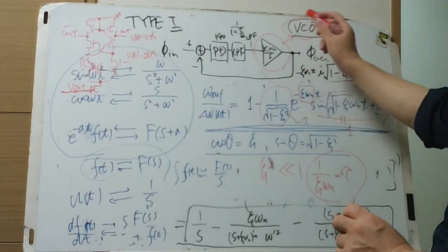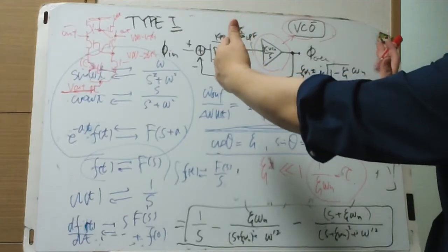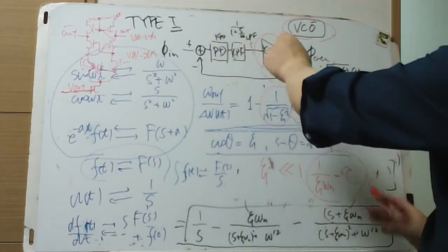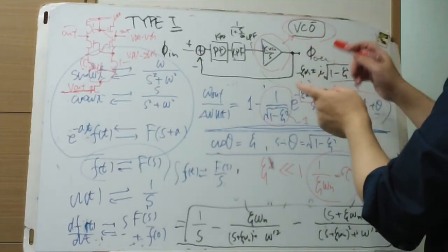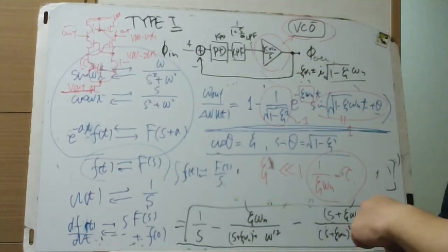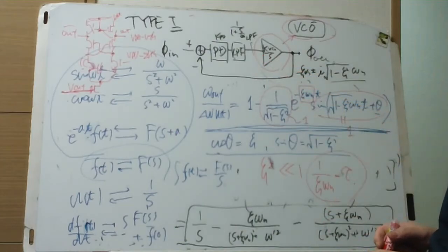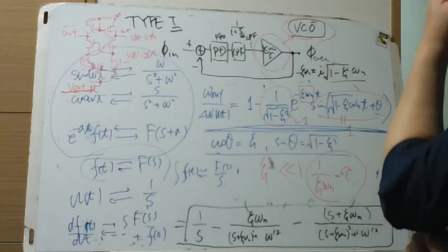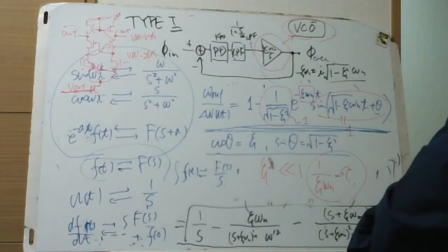And the VCO is more important. How large a bandwidth can it linearly generate, how fast can it lock the phase and frequency, how stable is it, and also how little jitter does it generate?